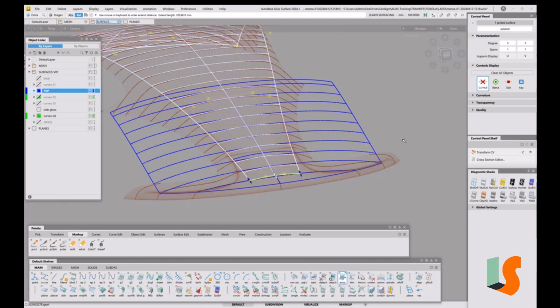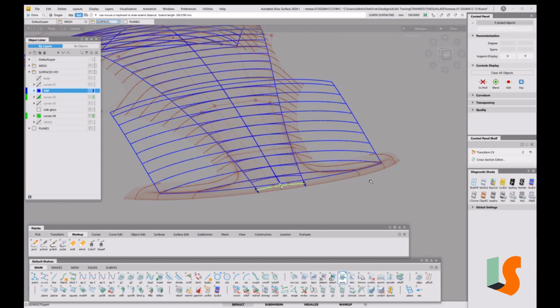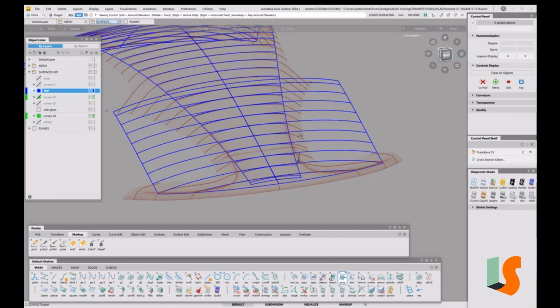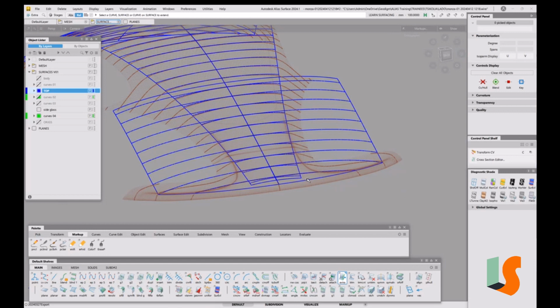We can see it curves down here, so we really want to extend it further. I could extend it all the way to the back edge, to be honest, and see what happens. And you can see it's still very curved. In fact, it sort of looks like it's curving more as we extend it. So by extending it, we're just getting an idea of where this surface is heading, whether it's actually getting flatter or what it's doing. Doesn't mean I'll trim convert it at that point or anything. It just means that by extending it, I can see what's happening.